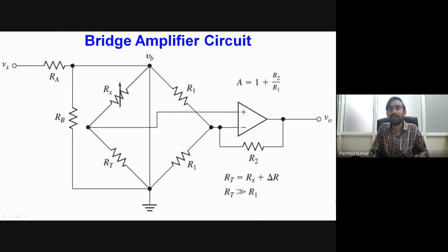Many times you will find that if we plot the value of pressure in our desired range of measurement, say if some transducer is measuring pressure from 0 to 5 bar gauge, and on the abscissa we have our current value, then when the current is changing from 4 to 20 milliamps, we will have a linear fit between the value of the current and pressure in this particular range of measurement.